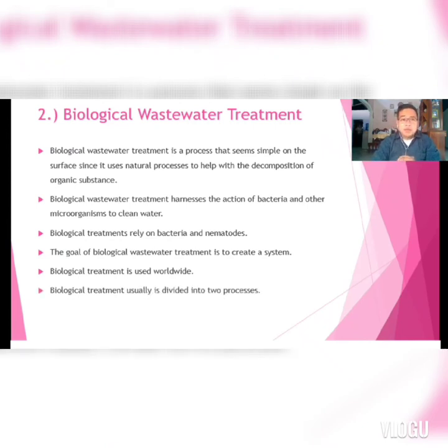Biological treatment is usually divided into two processes. First one is the aerobic. Microbial reaction takes place in the presence of molecular or free oxygen. Reaction products are carbon dioxide, water, and excess biomass. It suits wastewater with low to medium organic impurities, or chemical oxygen demand of less than 1,000 parts per million, and wastewater that is difficult to biodegrade, for example, municipal sewage and refinery wastewater.